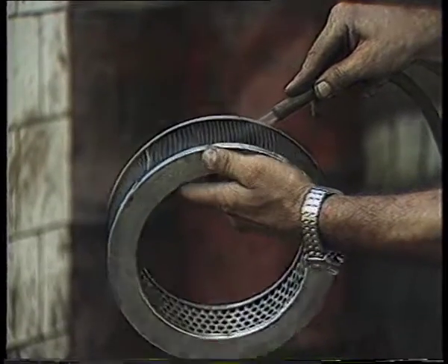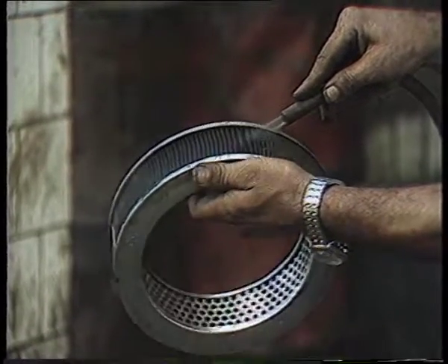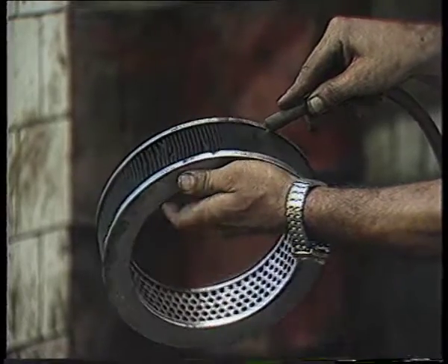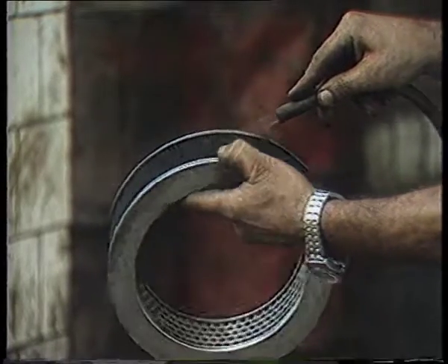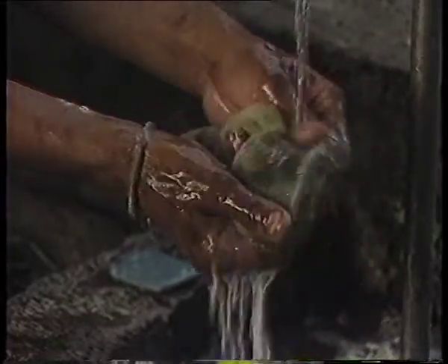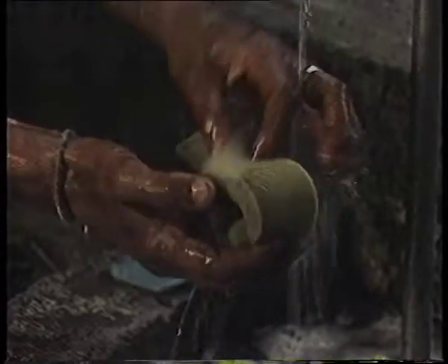The air cleaner filter element should be cleaned with an air blower to remove any dust particles. In case the filter is made of sponge, as in modern motorcycles, it should be detached from the filter body carefully, washed properly with soap, rinsed, and dried in a dust-free atmosphere.